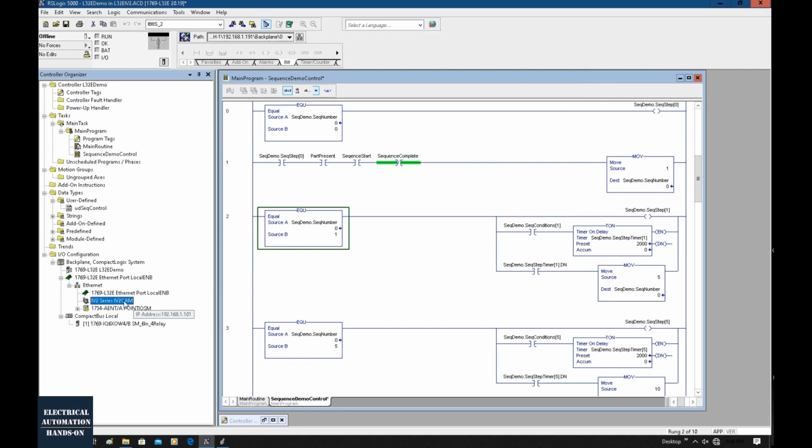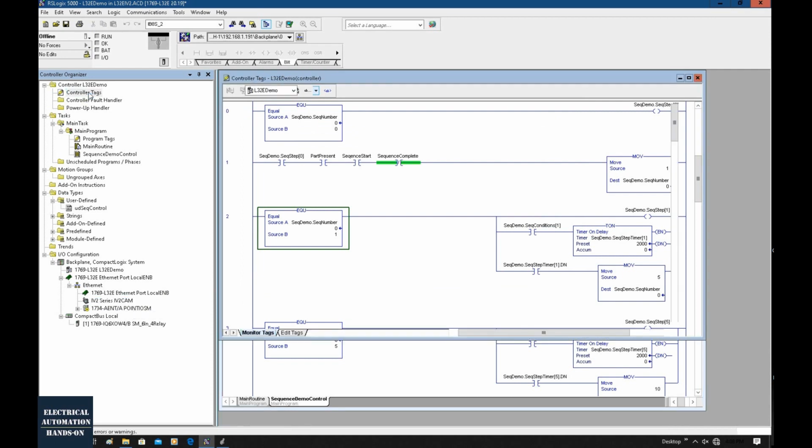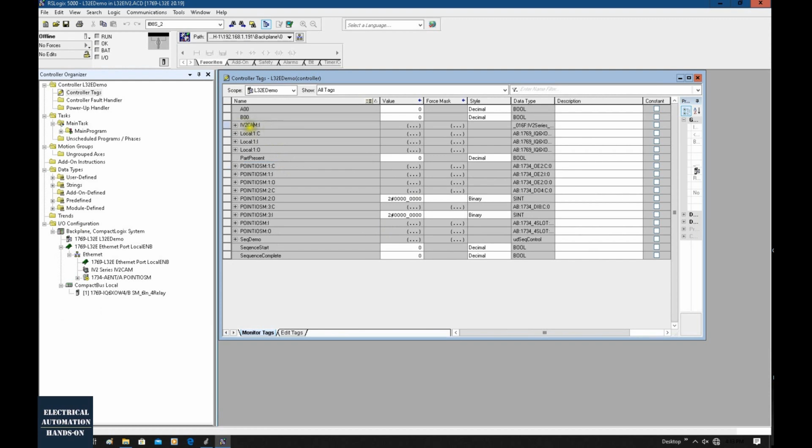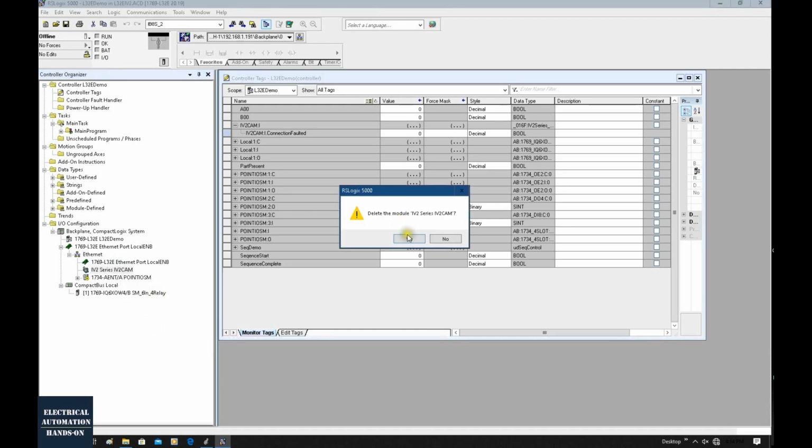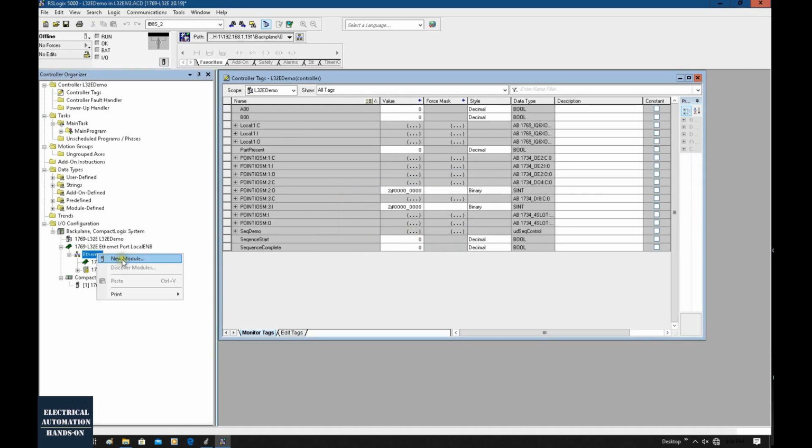Alright, we created this Ethernet IP device. Let's go to the controller tags, and we will see this IV2 camera. It only has this connection faulted. It doesn't show the input and output. That means this EDS file has something wrong. Alternatively, we can manually set up the generic connection here. We need to manually type in the assembly input and output. So this EDS file, for some reason, doesn't work. So I will delete it and manually create that generic connection. Let me delete it and add the new module again.